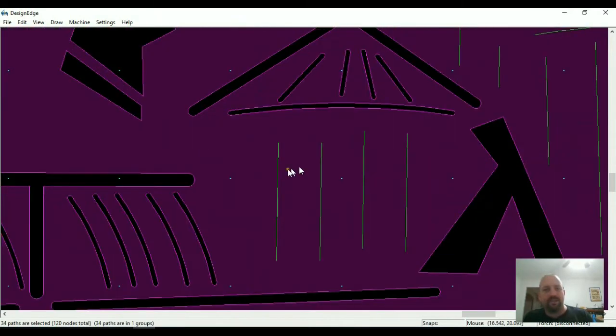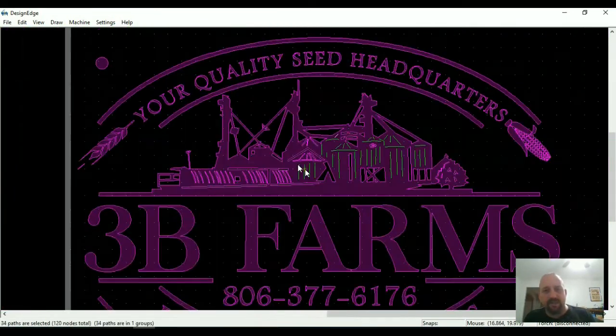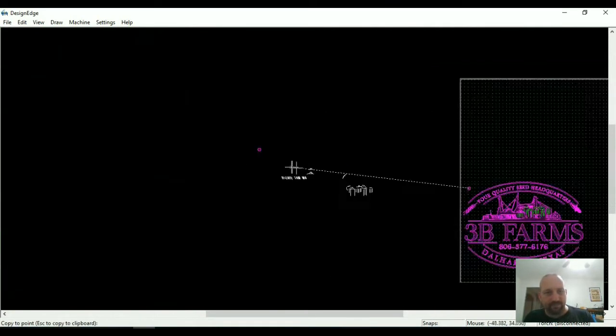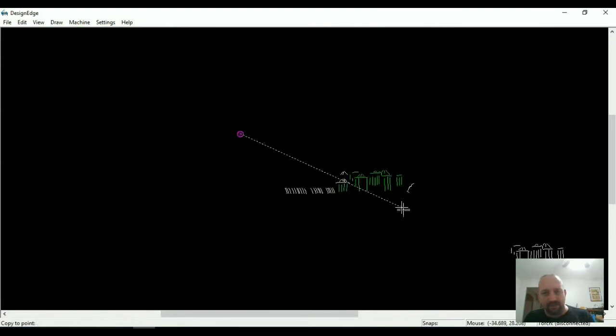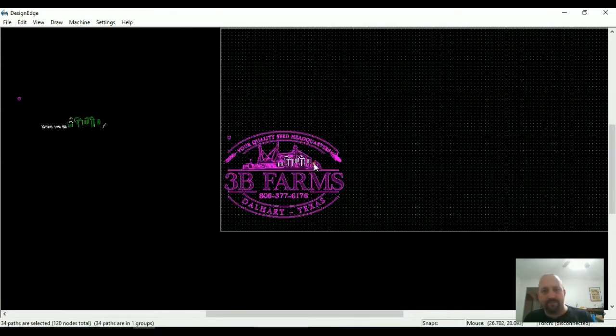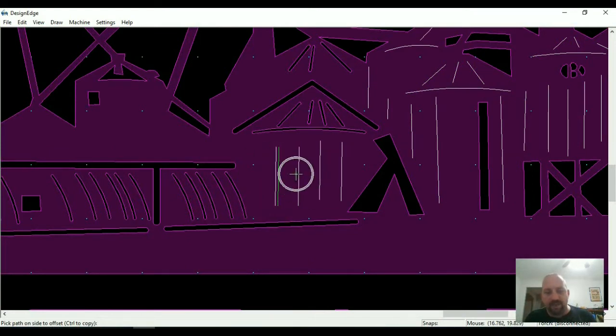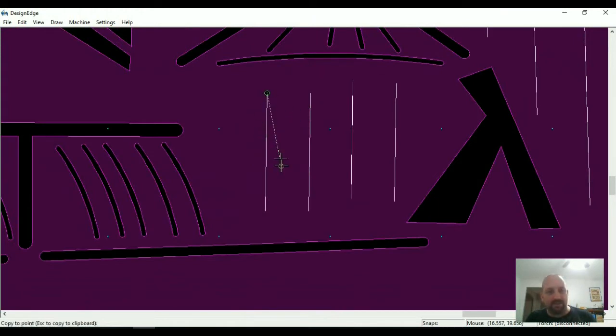them offset. So offset 0.045/2. Well, to make this easy, I'm going to copy those from the center and then center, so they're all in the right spot over here now. That way I can go ahead and ungroup them. I can do them the way I want and not have to spend so much time trimming them out. So Q 0.045, endpoint, center. We'll just put circles on the ends of them.